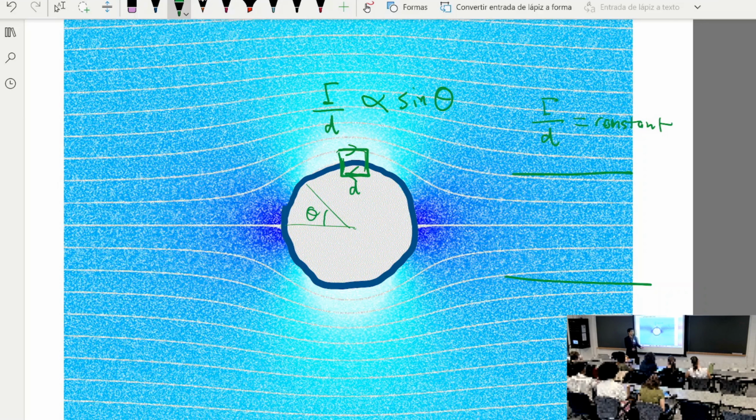We can integrate the pressure to get force, right? And then we can integrate the pressure times its lever arm to get moment. So from there, we can relate the shape of the airfoil all the way to the aerodynamic performance, which is lift and moment.